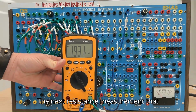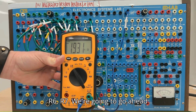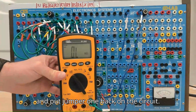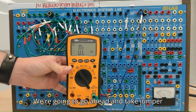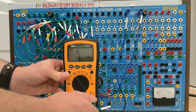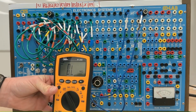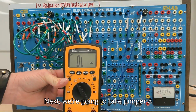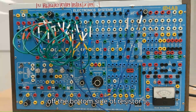The next resistance measurement that we're going to complete is R6, R7. We're going to go ahead and put jumper 1 back on the circuit. We're going to take jumper 8 and install it back in the circuit. Jumper 8 will go to the top side of R6. Next, we're going to take jumper 8 off the bottom side of resistor 5.